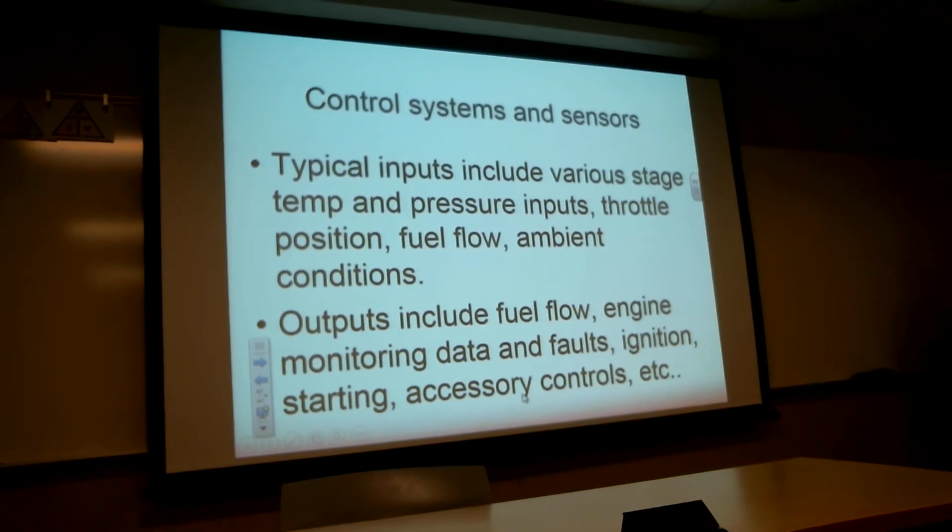Now, this little PMA only puts out about 15 or 20 amps, but that's all that's necessary to keep the engine running. So it's like a standby power source. Standby power source, yes, exactly.